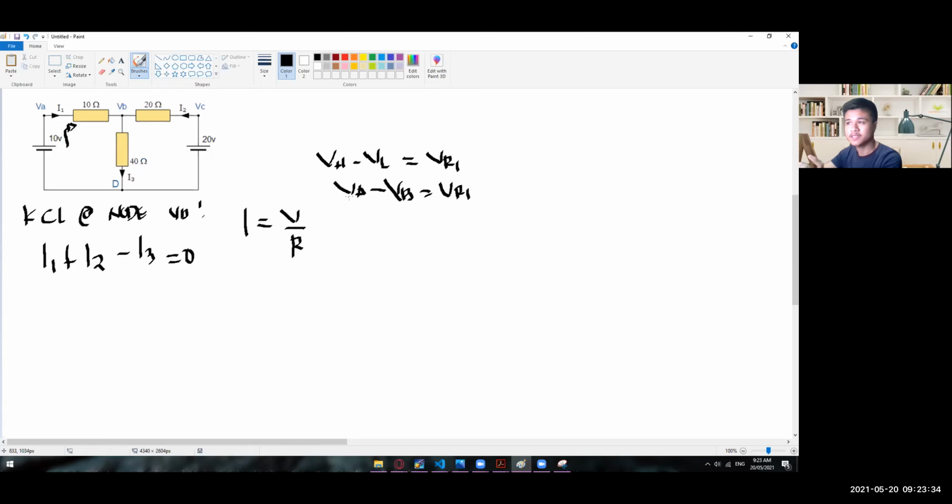That is why we have the expression VA minus VB. Here we're just simply going to put it as the final voltage across VB. So we have VA minus VB divided by R. What is this R? Let's just name these R1, R2, and then R3, so divided by R1. There you go, that is now our first expression for the I1.